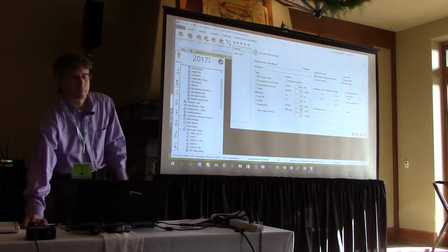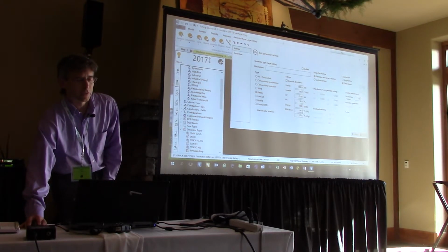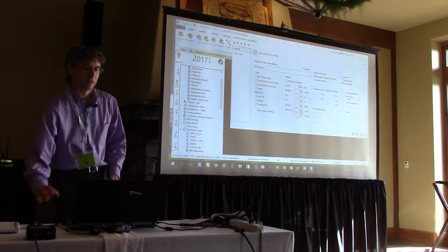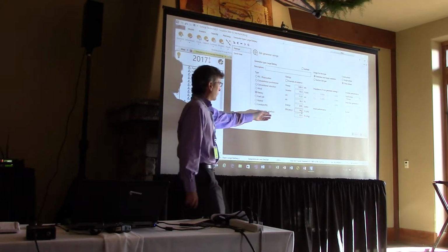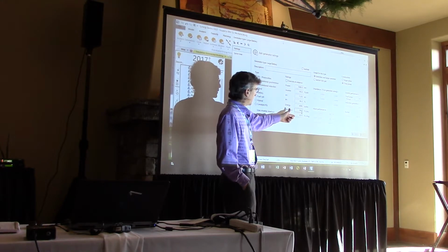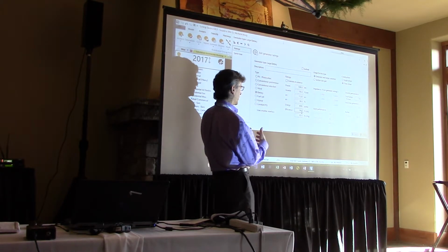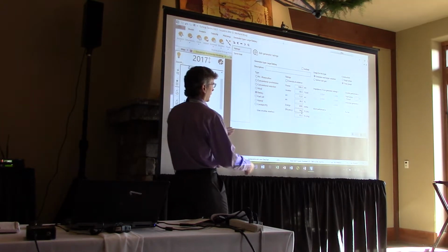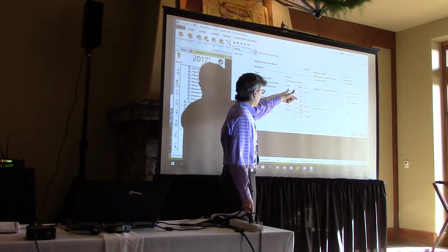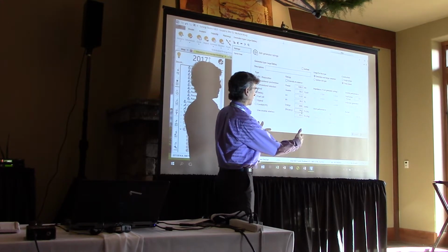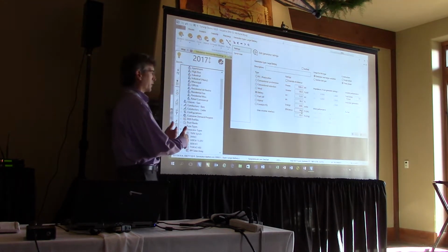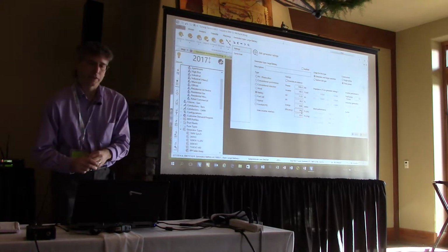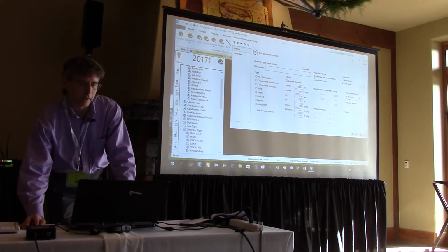It's neat. I think when you start studying these batteries, the efficiency has an impact on the schedules, because our batteries are usually schedule driven. These are pretty typical values, 84, and so you've got a schedule that says, okay, my battery needs to be discharging for this period of time. Well, it may run out of its energy level, it may dissipate before it has a chance to hit that full production. And then it may take longer to charge than you expect. So it runs shorter and takes longer to charge. And then the ramp rate, all that kind of stuff we're dealing with. So there's a lot going on the battery side.